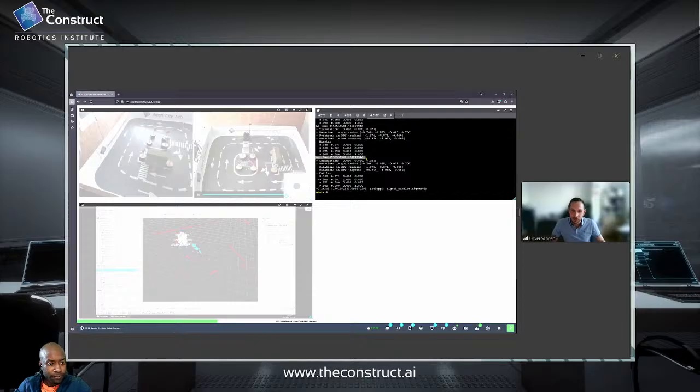So for example, at this specific point in time, it was transformed from base link to the wheel left link with that translation. So we have those X, Y, Z coordinates, or like the transformation, and then also the rotation in those different ways. Though, for example, the rotation with the wheels, especially since the wheels are moving and rotating, of course, this will always change depending on how we are using the robot. So, for example, right now, since the robot was standing still, those were pretty much the same. But if I would move the robot now, this would change. But still, the translation would stay the same because we are not moving the wheel from the base of the robot away, but it will always stay in the same position. Yes. Okay, so this is, let's say, the first step.